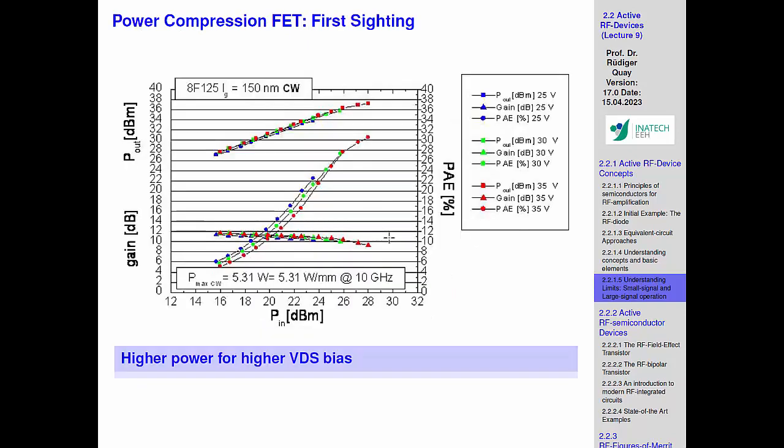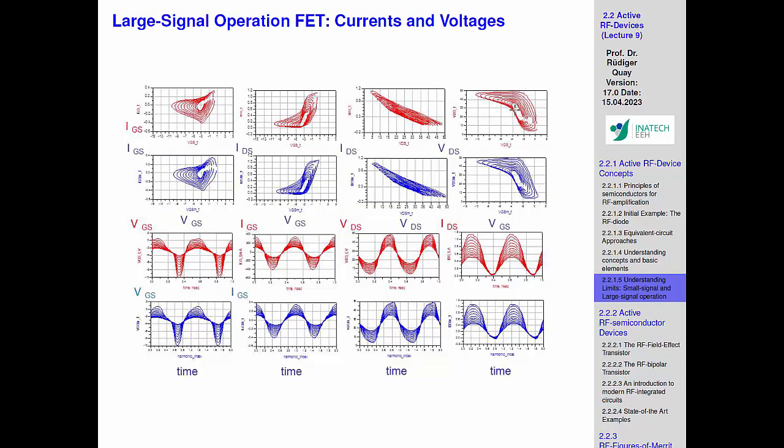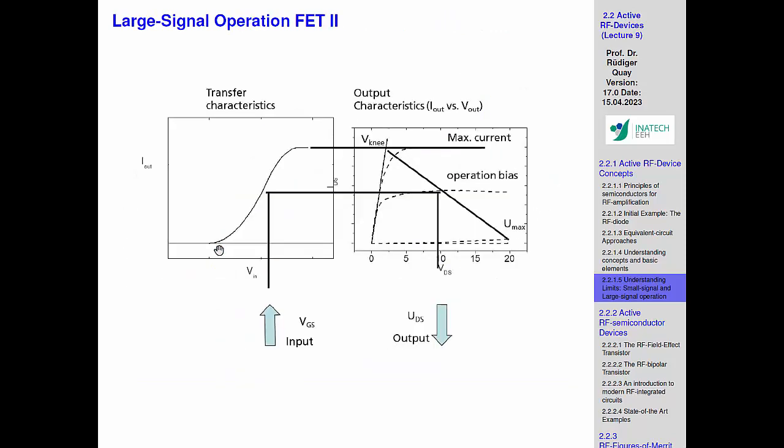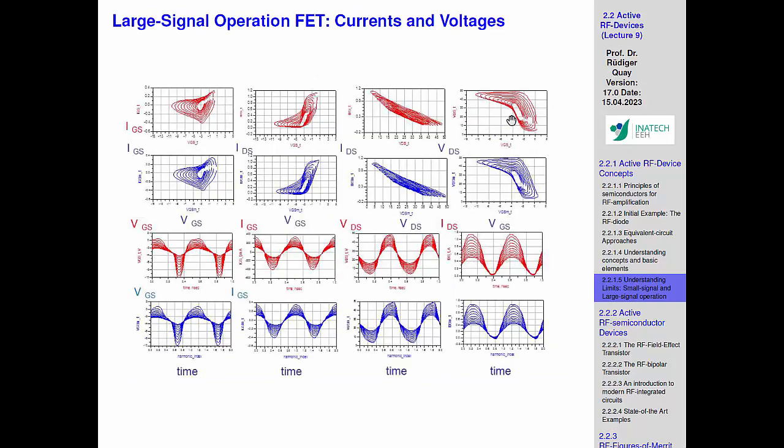And the capacitances you see here in this blowing up of the curve. So this is, for example, the simple characteristic of the output current over the input voltage. This is this here, but it's blowing up. And why I like this is something you know, because we know there are capacitances in this FET. And if you think from a power perspective, what do you get? You get real power and imaginary power.